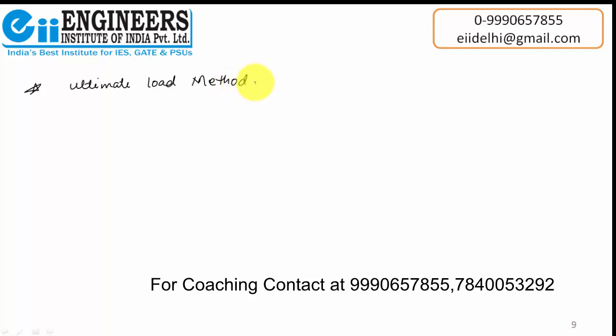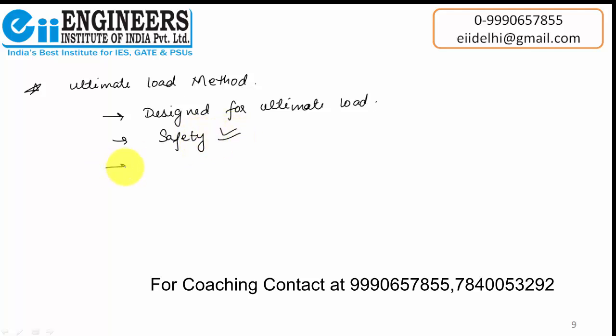In this, the non-linear behavior of material is also considered. Therefore, it is designed for ultimate load. But still it does not give the serviceability requirement. It does give the safety requirement, but it does not give the serviceability requirement. That is the reason we do not use it anymore.